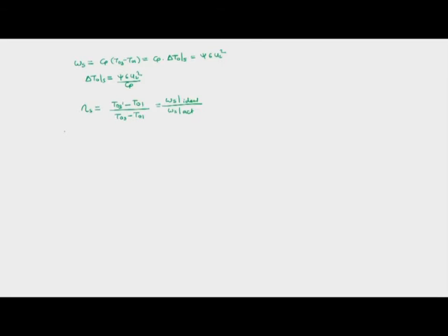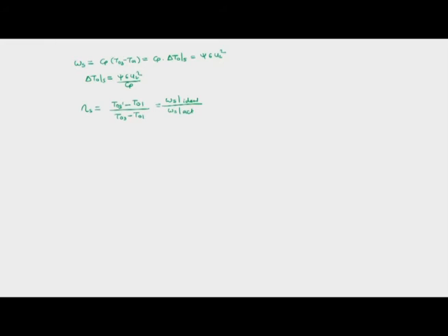When we considered the thermodynamic cycle earlier, we were considering static temperatures, not total temperatures. However, this is an improvised formula where we also consider kinetic energies. So T03 dash minus T01 is equal to stage efficiency into (T03 minus T01), which is stage efficiency into delta T0 stage in the actual case.